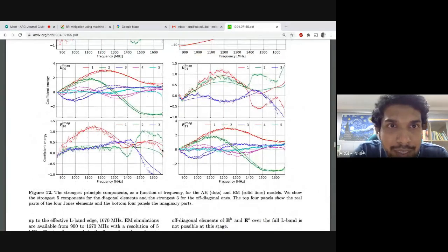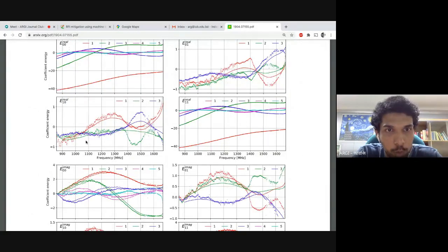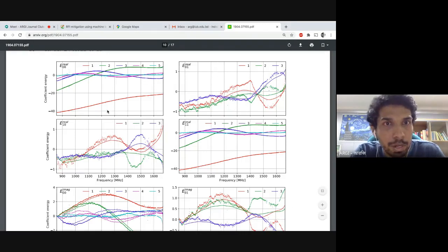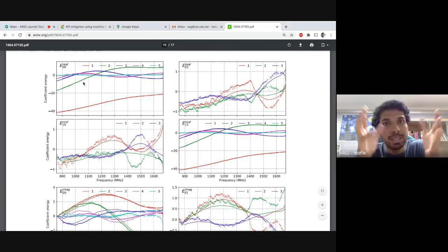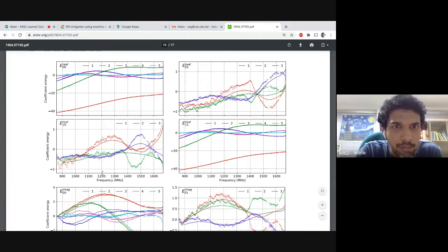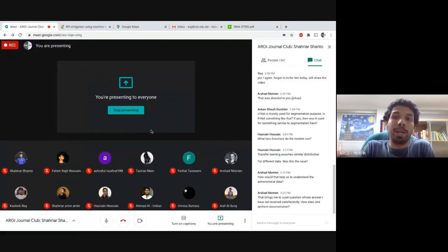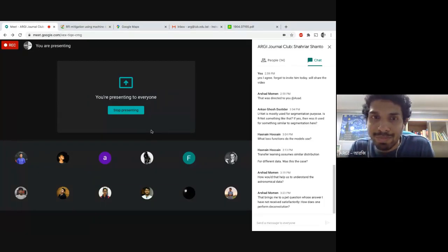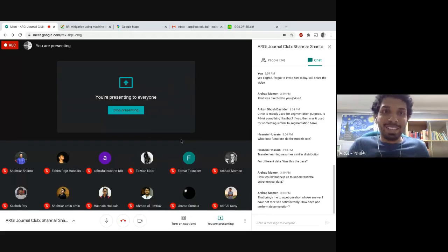So for example, if you check this curve here, this is the frequency behavior of those models, going from 900 to 1600, let's say 1 gigahertz to 2 gigahertz. Now you'll see that in many places, the data is really bad. Basically, the places where you don't have data because of RFI. So there are at least 3-4 different patches within this frequency band. One patch would be around 1100 to 1200. Another patch would be from 900 to 1000. Another patch there. So here you can see a lot of scatter. Those 3-4 bands within this frequency range will be affected using this mechanism.